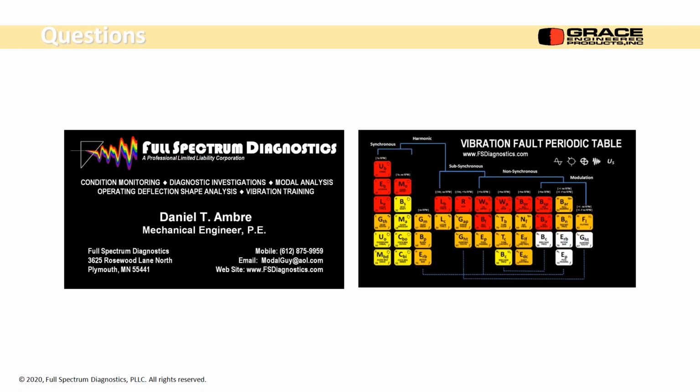I guess statistically, you'd have some noise floor. So the scrap going through is going to be random. So you're going to have an energy level. You'll see the peaks, you'll still see the blade pass and the rotating speed and things like that. It'll just be a noisier spectrum.